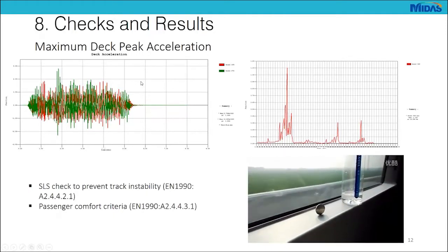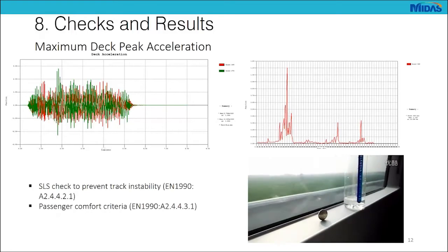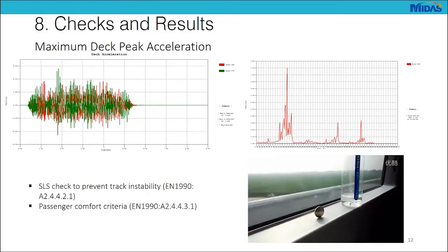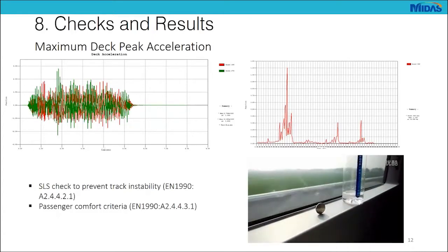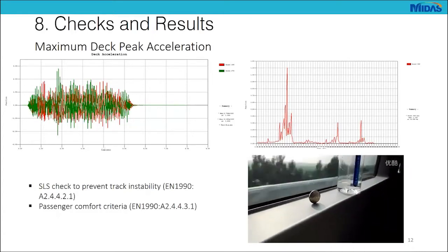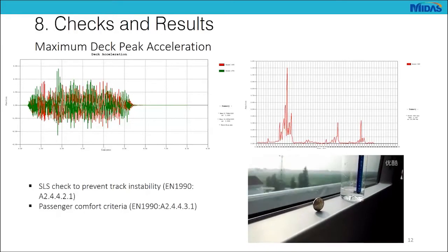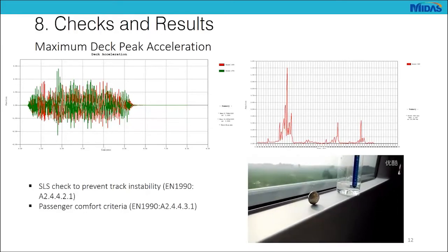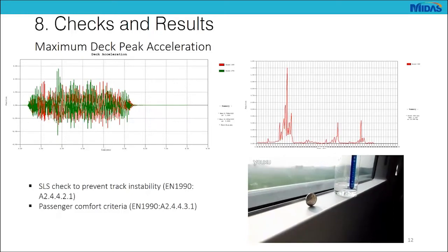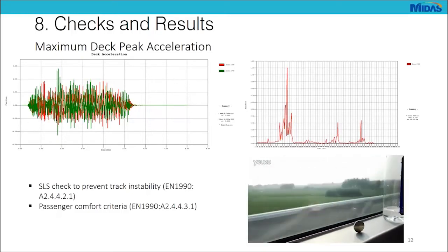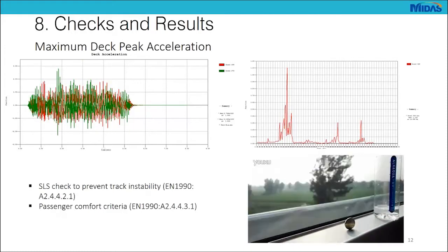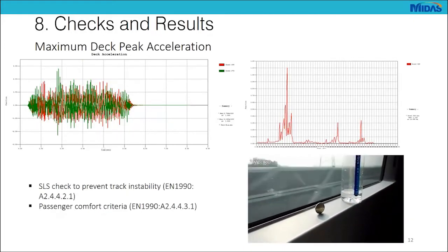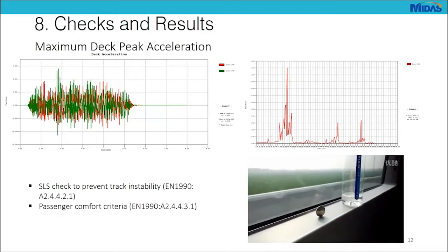And then once we've made sure that the acceleration value is not passed, so the requirement is fulfilled, we are also interested in making sure that the excitation applied to the structure coming from the train load does not match the resonance of the structure, does not match the vibration properties of the structure. So we don't want to have the same frequency as the frequency of the structure.